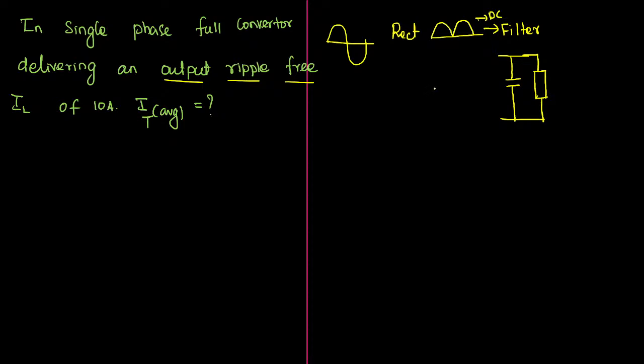The natural behavior of the capacitor will be, it will simply act as an open circuit with a constant voltage. The capacitor will charge up to the maximum peak voltage of the pulse. First it will be charging up to the maximum value of the supply pulse. So once it is charged up to the maximum value, then it will discharge if there are any loads available in the circuit.